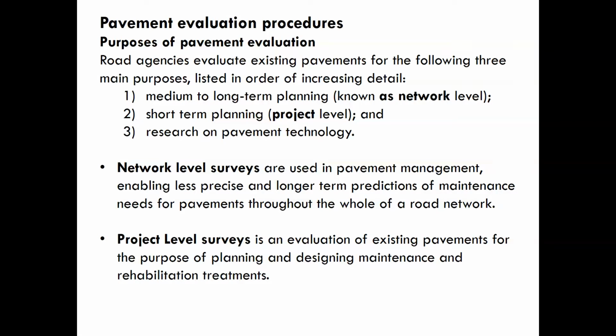They might need to choose just a sample of the road to do the survey, and they could do it on foot for a stretch of road which is not too long, or inside the vehicle. Sometimes they call it the visual survey by vehicles, or we just call it the windshield survey. So this is a network level survey, with the intention for medium to long term planning.